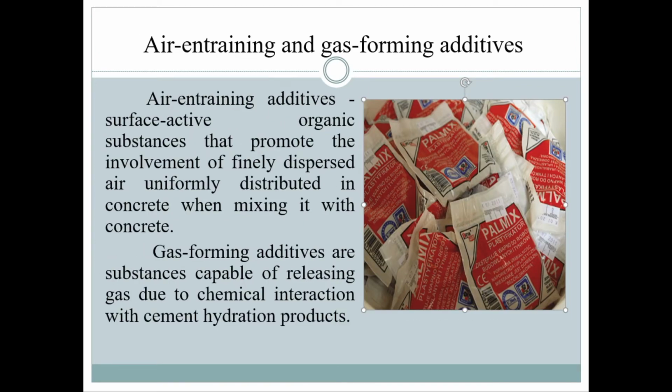Air entraining and gas forming additives. Air entraining additives are surface active organic substances that promote the entrainment of finely dispersed air, uniformly distributed in the concrete when mixed with concrete. Gas forming additives are substances capable of releasing gas due to chemical interaction with cement hydration products.